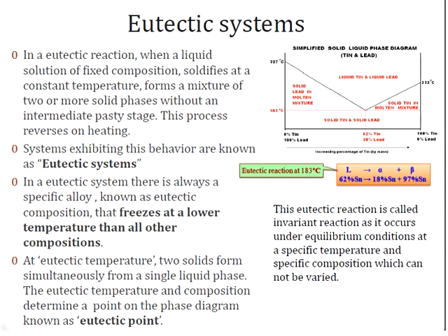Now we discuss the eutectic system. The eutectic is a Greek word that means low melting point. A eutectic reaction is a three-phase reaction by which, on cooling, a liquid transforms into two solid phases at the same time. So it is a phase reaction but a special one. For example, a liquid alloy becomes a solid mixture of alpha and beta at a specific temperature. So this is happening at a particular specific temperature.